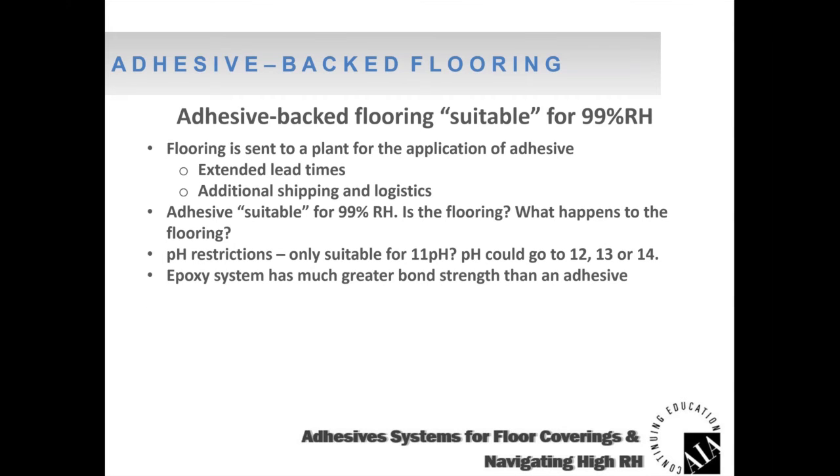Epoxy systems, such as the two-component epoxy mitigation systems that are out there on the market, and there's several different manufacturers. I want you to understand that the bond strength of a two-component epoxy to a concrete substrate is much stronger than an adhesive, and that's coming from a manufacturer that not only makes adhesives, we also make epoxy mitigation systems. So we truly understand that.